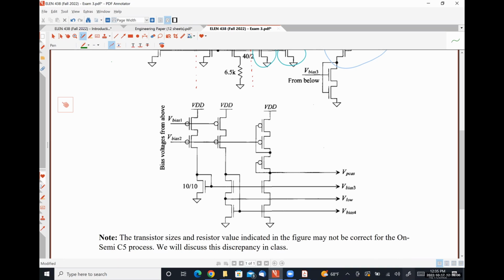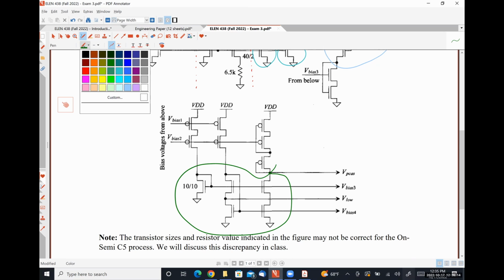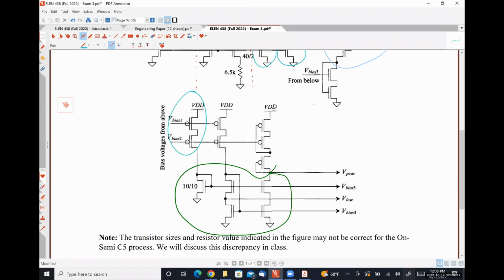And then down here, these are all part of the same circuit. We have our wide swing NMOS current mirror. Two cascode current sources serving as our biasing reference currents for that wide swing current mirror. We have another bias for the other part of our push-pull output stage. And then we have a little cascode here to provide the right amount of current.